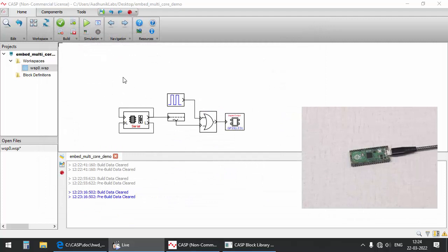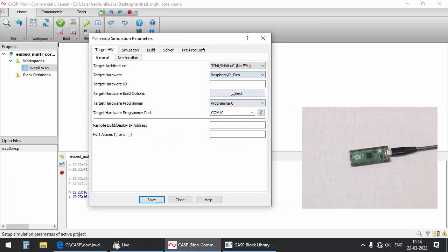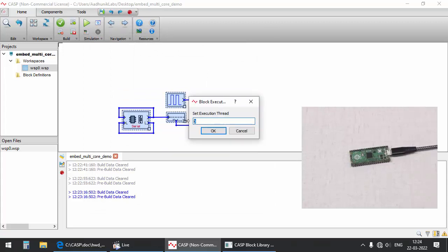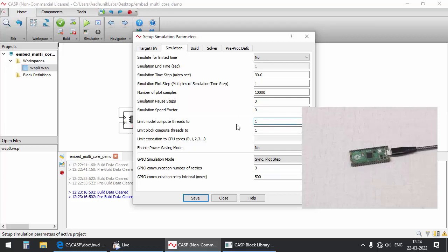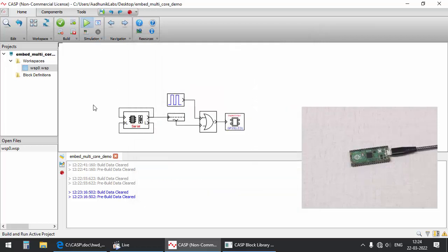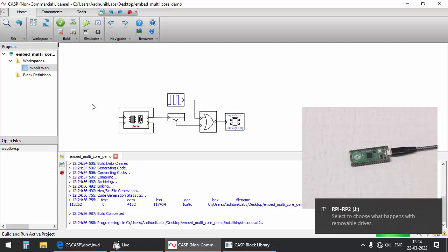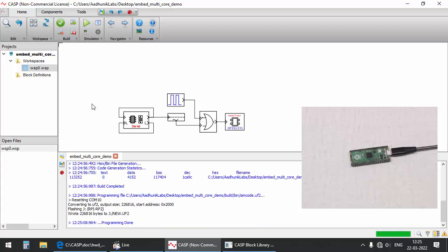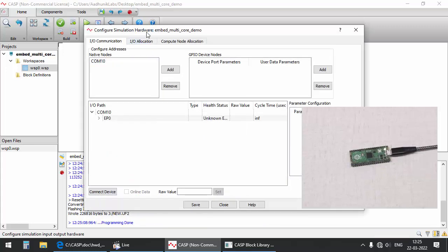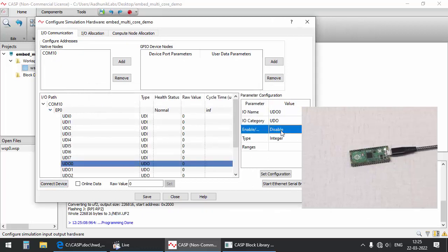We now demonstrate how to program Raspberry Pi Pico board using same model and following similar steps. Initially we run the complete model on single core. Take a note of the rate at which the LED is blinking with and without serial communication. As expected, the LED blink rate reduces when serial communication is on, compared to when it is off.